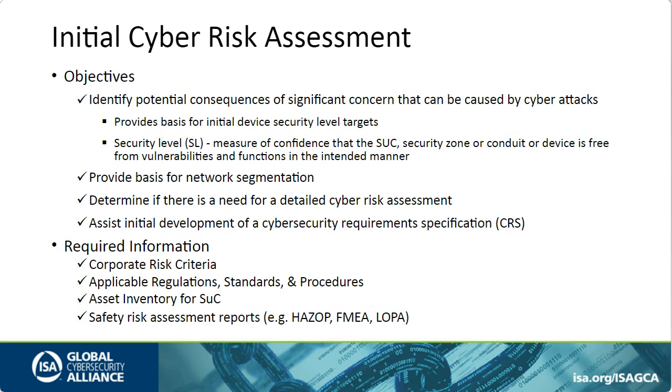An example of one that is not would be a mechanical pressure safety relief valve or a rupture disc, for instance. That's not really vulnerable to cyber attack. But if you've got something like a burner management system, where you're controlling a fired heater or a boiler, you can have some significant hazards associated with a firebox explosion, and there it's all instrumentation, pure and simple, and it's vulnerable to cyber attack.